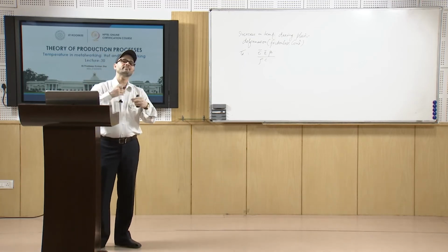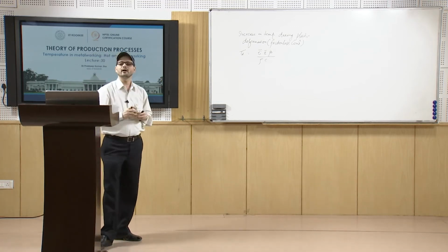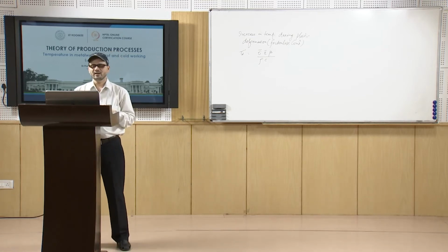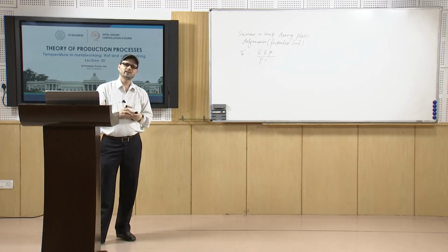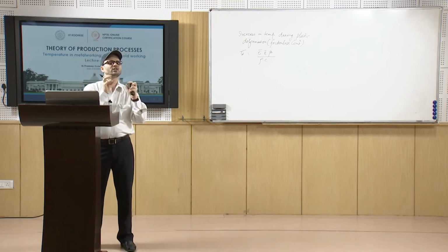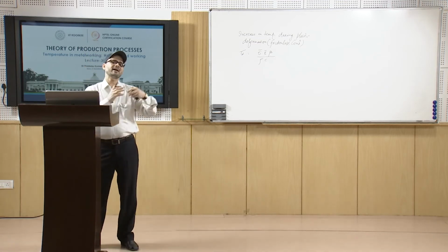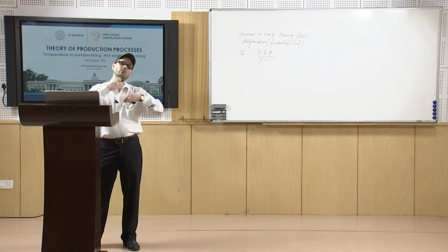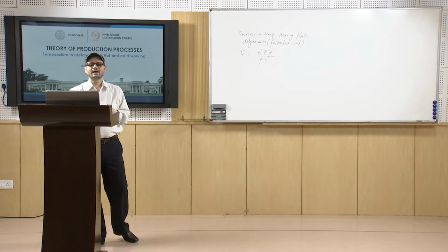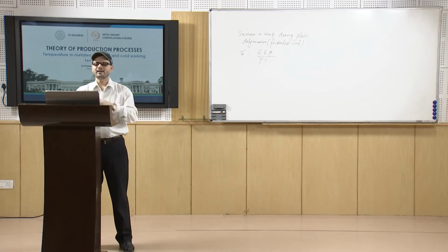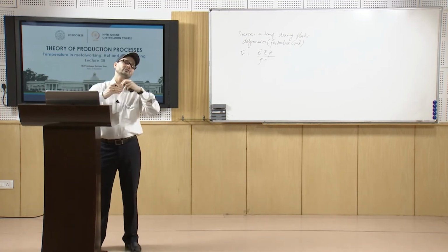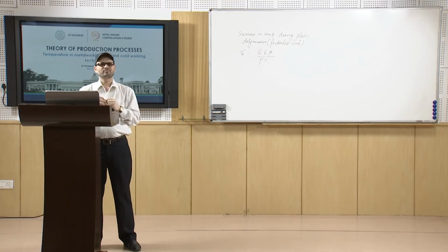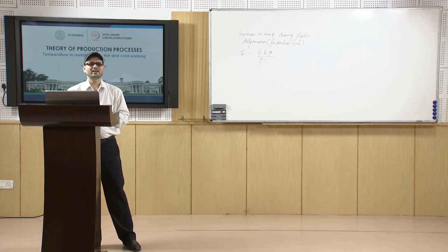Similarly, you will also have the temperature increase because of friction. The previous case is when you do not take the friction into account, the case of frictionless deformation. Now, for friction, again a similar expression will come. It will be rho c into V, multiplied with Tf, which is the increase in the temperature because of the friction, and that will be equal to mu times P into A. That will be the force, multiplied by velocity, and then multiplied again by the time interval of consideration. So, that will be equated. That is why Tf, the increase in temperature, will be mu P A into V into delta T, divided by rho c into V, that is the volume.